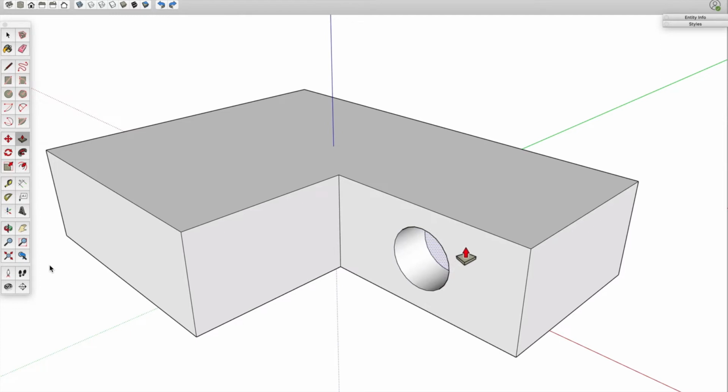Don't worry, if SketchUp tries to infer things along the way that confuse it, just keep moving your cursor confidently back through. Now at this point you can't see what you're doing. But if you keep going, you'll eventually notice that the push-pull is going not only through as a tunnel, but it's actually going even further. That's not good either. We just want to create a tunnel through this, not something that extrudes out beyond.